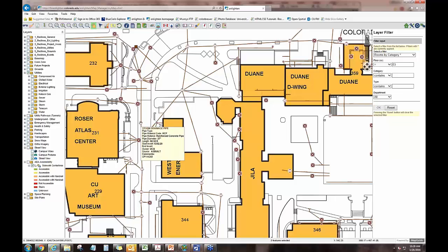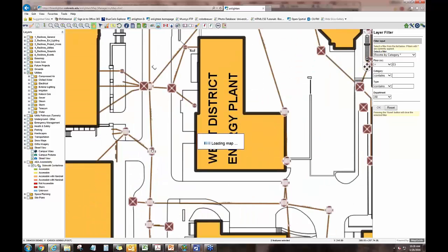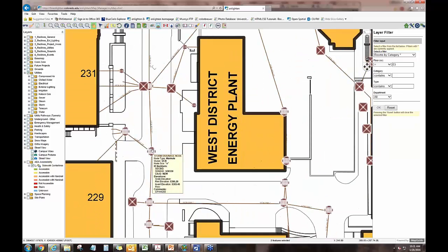And so you can see we've got a lot of these populated with owner and invert. So let's see. Yeah, there's a complete one. That's where they dug up both ends of it, and they could tell us that the start invert was there and the end invert. And we've got a lot of inverts on these manholes too. So we are backfilling a lot of that information.